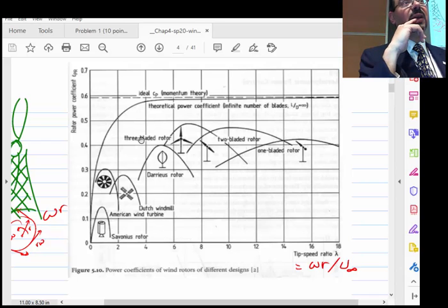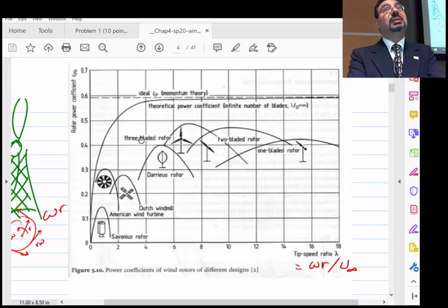Betz's limit, yeah. We are trying to explain why that Betz limit does not apply to a hydraulic turbine, because the waters are connected through the turbine, whereas the wind turbine is open. No, I don't think the confinement of the tube is really the reason.